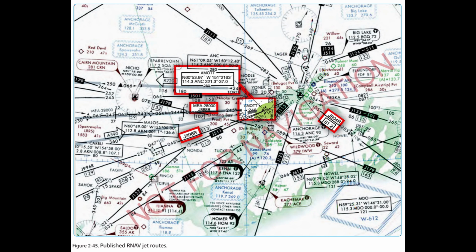Increasing use of self-contained airborne navigational systems that do not rely on the VOR/VORTAC/TACAN system has resulted in pilot requests for direct routes that exceed NavAid service volume limits. These direct route requests are approved only in a radar environment with approval based on pilot responsibility for navigation on the authorized direct route. Radar flight following is provided by ATC for ATC purposes. At times, ATC initiates a direct route in a radar environment that exceeds NavAid service volume limits. In such cases, ATC provides radar monitoring and navigational assistance as necessary.